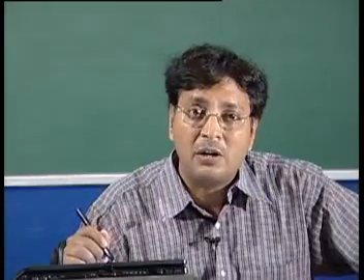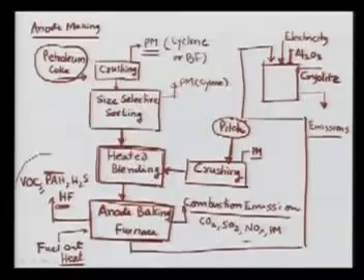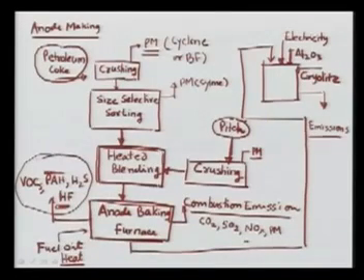these anodes were in the pot, and in the pot we are using a lot of fluoride, and that fluoride will somehow become part of the used up anode. Once they are brought back and used again, some fluoride emission can also take place. So you can see here that it has very high potential for air pollution, and also the potential for very carcinogenic toxic compounds which can cause serious problems in the environment. So you can see the emissions from the anode baking.